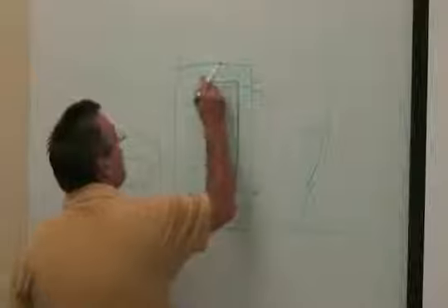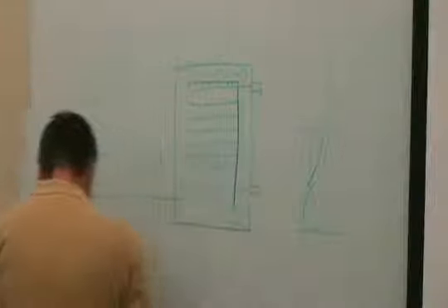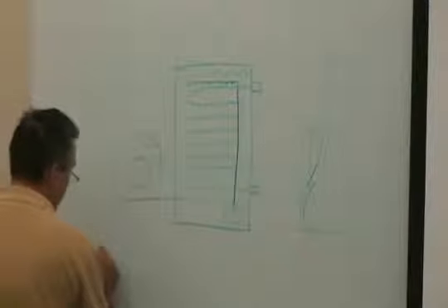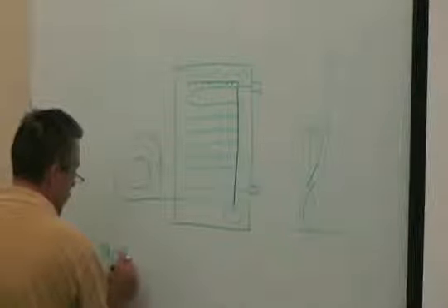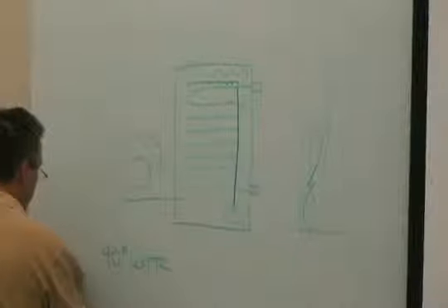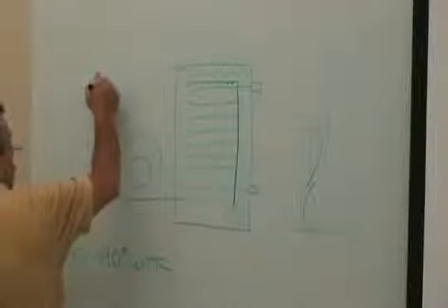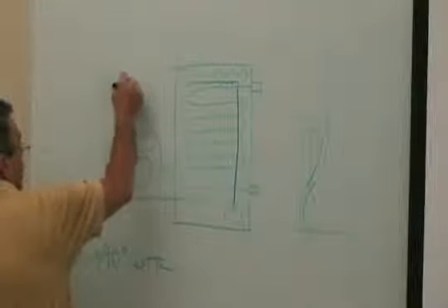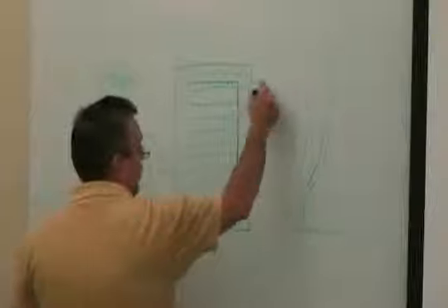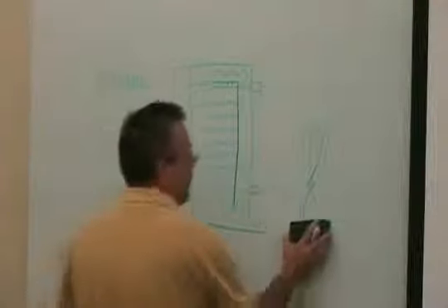comes up here, the distribution system, and just sprays water over the heat exchanger, and then you can operate and generally produce about 90-degree water with 100-degree water coming in. That would be called the fluid cooler. And we talked about this being the supply to the heat pump system. This is the return coming from the heat pump system.